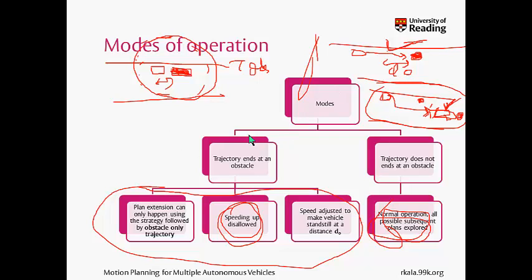So I have sensed this kind of scenario which I was very scared of, and I have said that when I have sensed it, I will make sure I do not go at a distance more than d0 from the obstacle. I'll brake myself well enough so that I stop before a distance of d0. Even this is a scary scenario where a static obstacle is here and I am at a distance of d0, but at least now I can wait for the other vehicles to go, wait for the road. Suppose there were two vehicles here, I can wait for both of them to go. I can wait for the road to clear, and when both these vehicles are gone, they are somewhere here, I can nicely steer myself here. So that is what I basically do. I sense this scenario, and whenever I find it, I stop at a distance of d0.